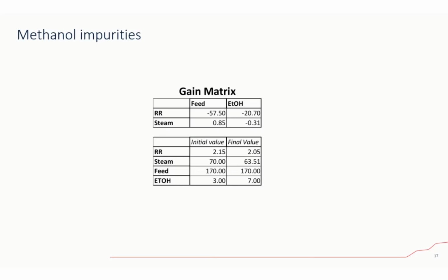So when you have simple columns that have a quick time to steady state, then chances are you are able to use an automated step testing tool, and that should be fine. And also when you don't have a lot of interactions.